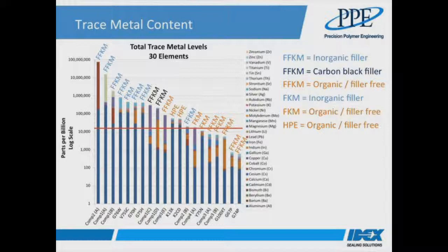So the other thing to note is that this is really where the organic materials get their own back for the thrashing that they got through most of the plasma erosion tests. We see that the best material grades are exclusively the organic materials, and the inorganic materials are again getting on for around an order of magnitude dirtier than even the worst of the tested organic filled grades.